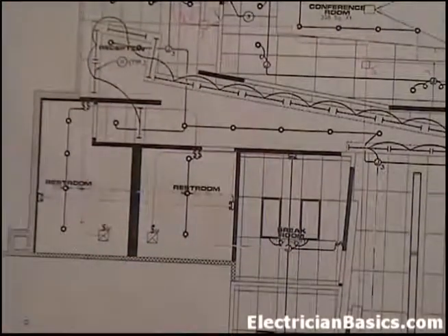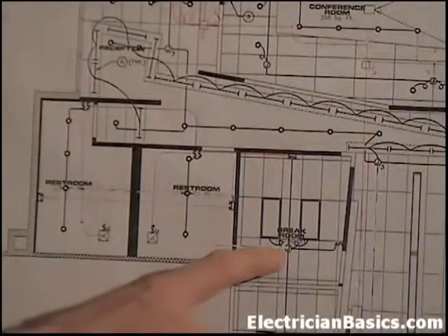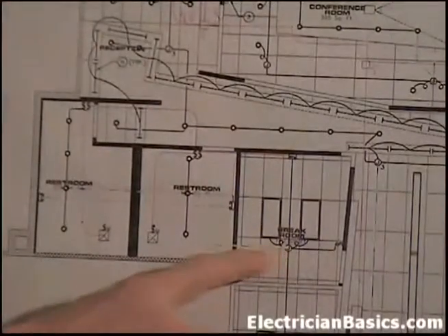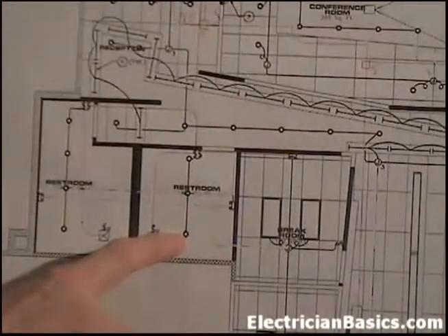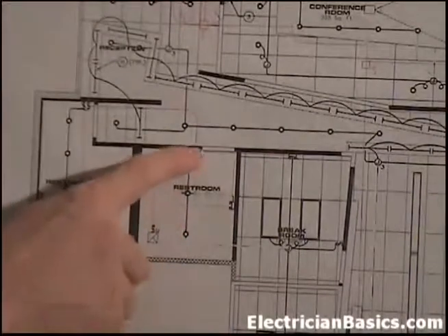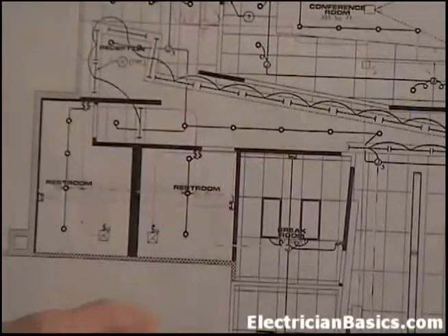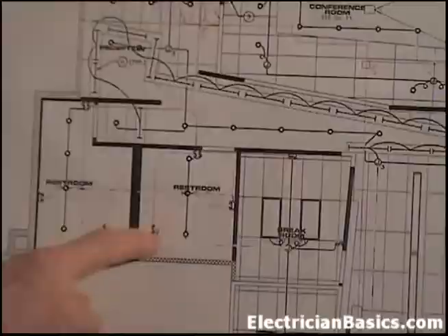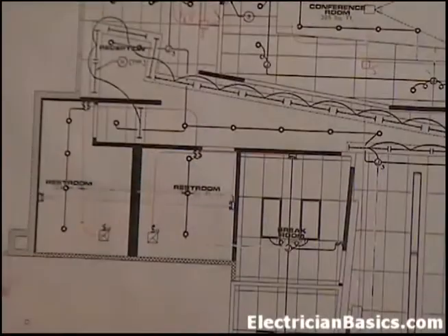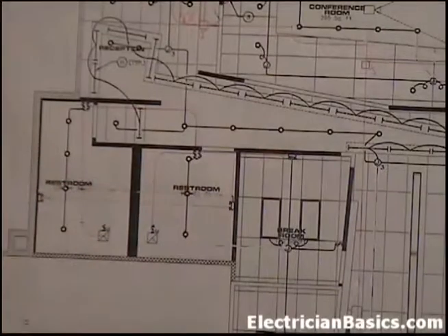Okay, now here's where it gets a little tricky, and here's where the electrician made some changes. You can see I've got a line that I whited out that goes into this bathroom to feed it, because the hot would be going to the lights. But we need a switch leg, so we'd have to take them through the switch, bring the switch leg back, and this gets packed in together. And it also whited out here to the fan, and again it'd be the same thing where the hot goes to it and we got to switch it and come back. And they're maybe switching it through the lights, which you really don't like to do.